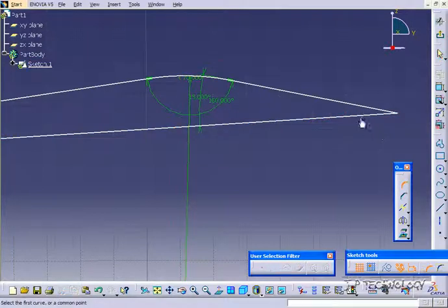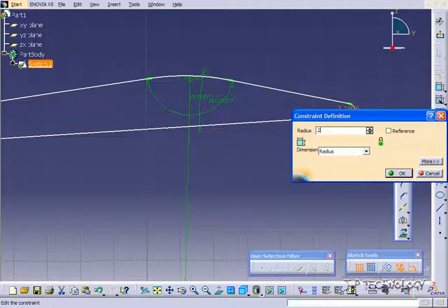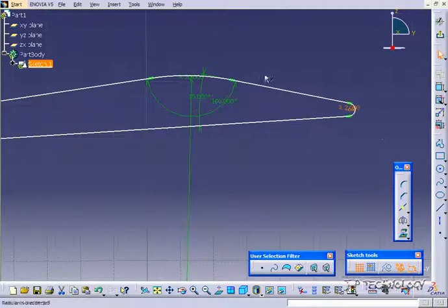So let's click corner, click this line, and with a small angle, it takes a very small rad to make a change. So let's throw the corner there, and you can see that the curvature change here is very dramatic compared to the curvature change here. Meanwhile, the rad here is only about 2, and let's put in 2, compared to 70 here. So when you have a larger angle, the rad change is going to be much smoother, and when you have a smaller angle, the rad change is going to be a lot more drastic.